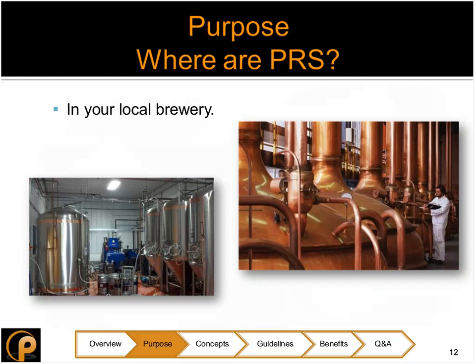Those lucky ducks in the brewing industry require pressure relief systems too. During the fermentation process, yeast digests sugars, which converts them to ethanol and CO2. In a controlled enclosed fermenter system, the CO2 generation, along with an airlock, is used to maintain a slight positive pressure on the system, which keeps airborne contaminants out. However, a blocked airlock might cause an overpressure.